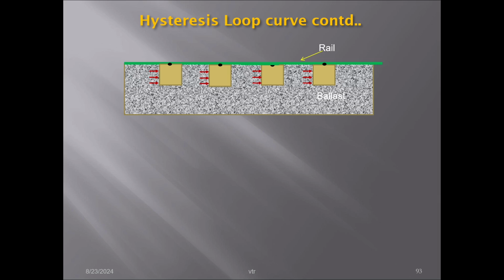Okay, double the resistance, because when the ballast offers some resistance, there is a fluctuation in the sleeper and under the packing, and it offers the resistance R, and expansion takes place. Immediately a reversal takes place, temperature decrease takes place. When it is coming back, it will not immediately become R. Whatever resistance it has has to come to 0, then one more resistance is required for counteracting the movement. So there will be mobilization of double the ballast resistance.